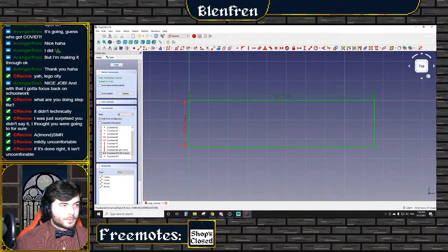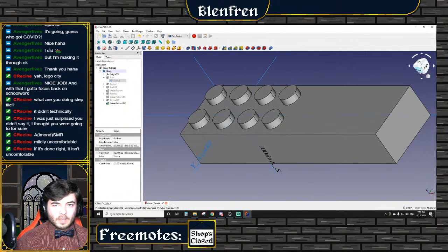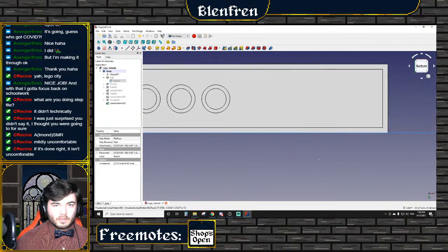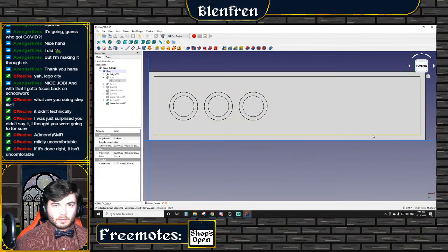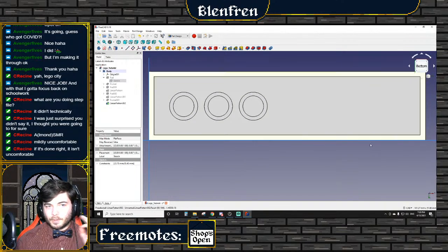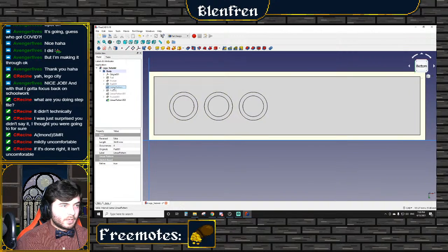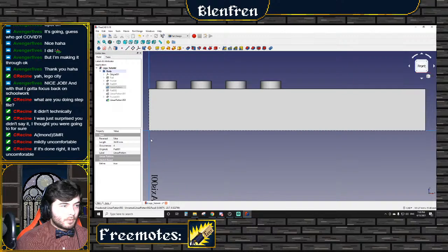And then we hit close. And then we've got this weird looking thing, but if we take a look at the bottom here, the extrude actually went with it, because it's based off of the distance between here, which is super good. It makes everything really easy, and that's what they were talking about earlier. So we don't need to do anything with the pocket. We do need to change the linear pattern of the pad, but we don't have to change the pad itself.